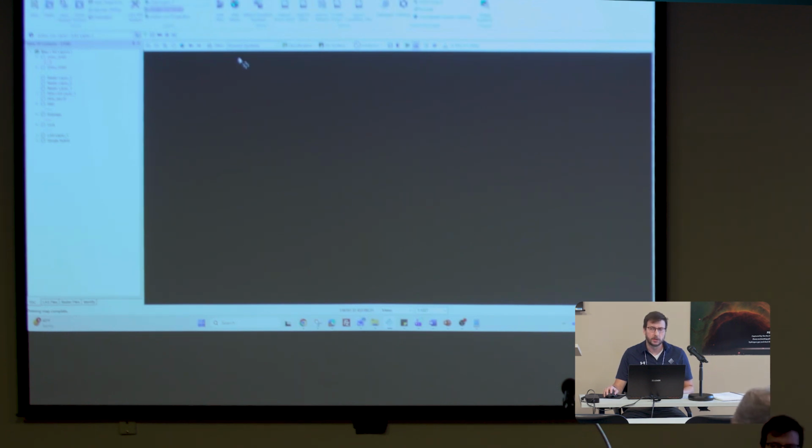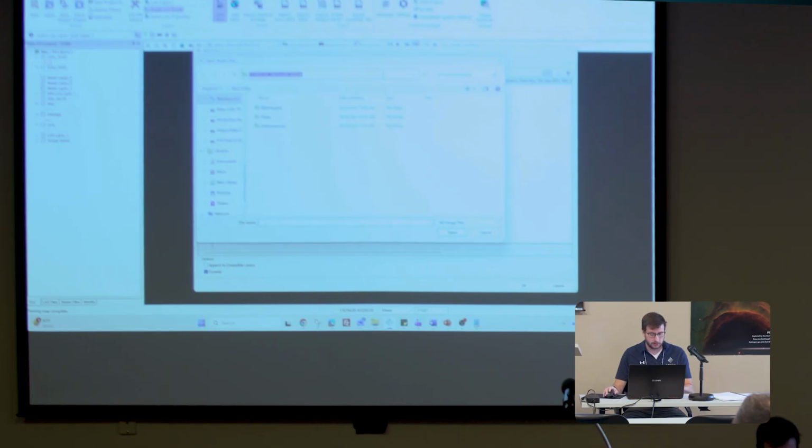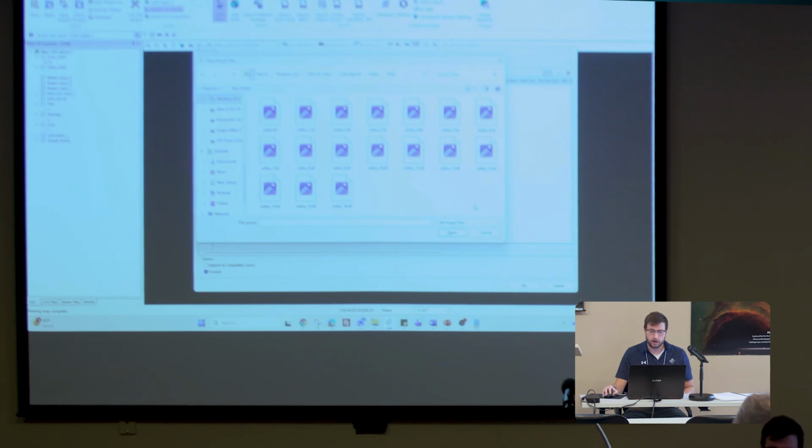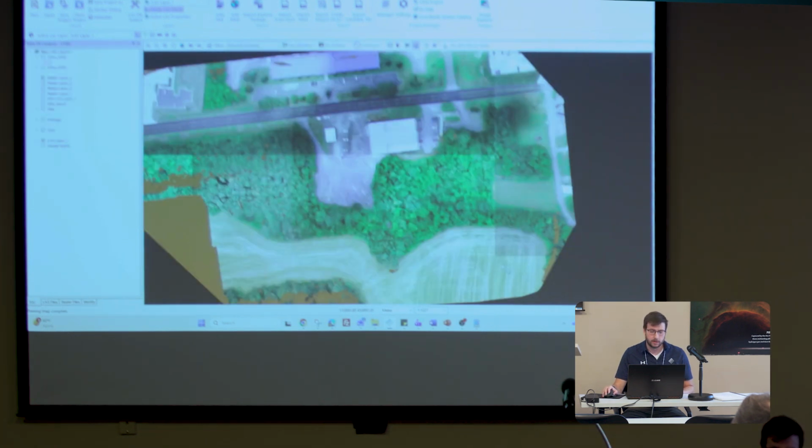If you want to combine a bunch of files into a single layer, click on the Add Files dialog at the top, click on the raster tab at the top, click the plus button, and I'm just going to do a Control-V. I'm going to input that location where all those tile files are, and then select them, click Open. So now I can re-import, and it's going to put these all on the same layer. I know these are already pyramided, so I can uncheck pyramid, and that'll go a little bit faster. Click Open. And now all those raster files, they're all located on a single layer.